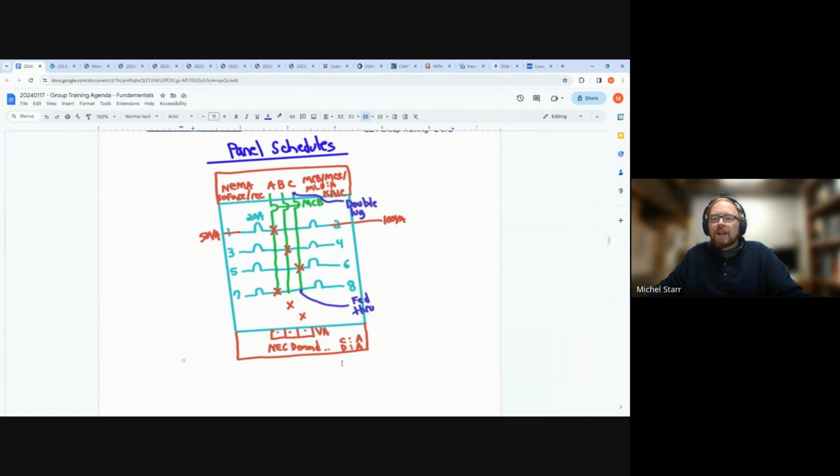And again, panels closer to loads might have some. So for instance, if you had 10,000 VA, which is volt amps of load, or 10 kVA of receptacle load, the code wants you to take 100% of that, which means that you can't reduce your sizes of your wire or your overcurrent protection. And then after that 10 kVA, you can take 50%.